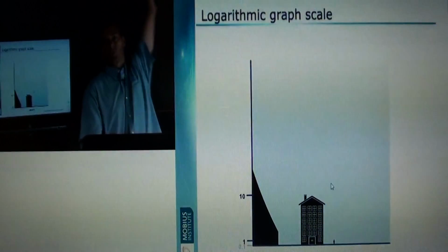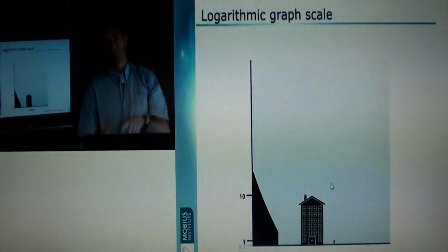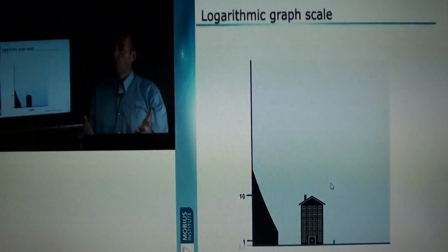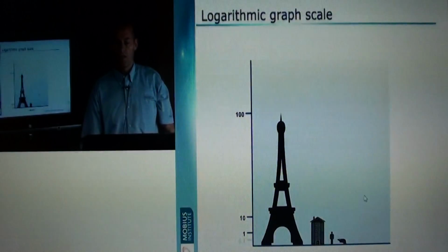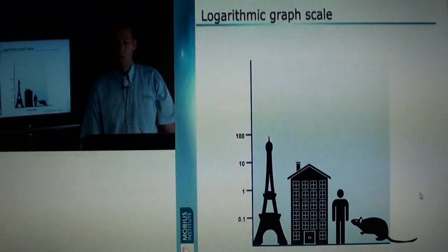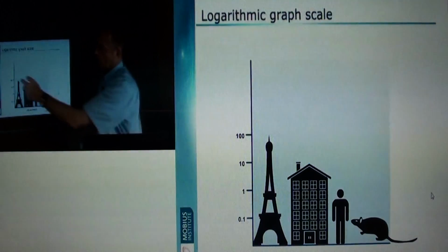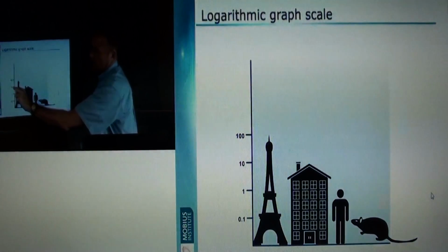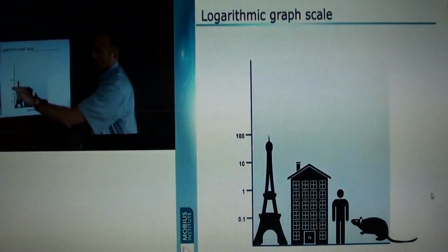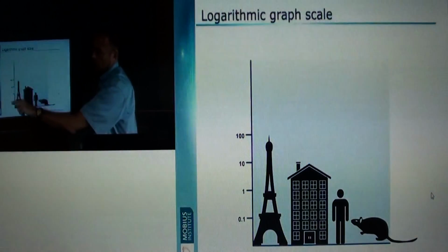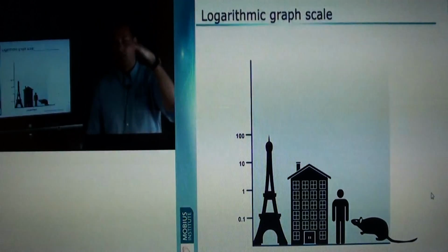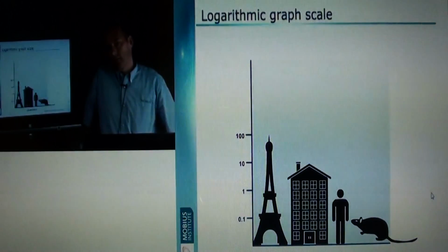You either need to have a computer screen that's this tall and you can see them all, or toggle to log. Because if you toggle to log, look what just happened to my y-axis. Now, the 10x peaks, 100 millimeters per second, 10 millimeters per second, 1 millimeter per second, 0.1, they're all evenly spaced down the graph.